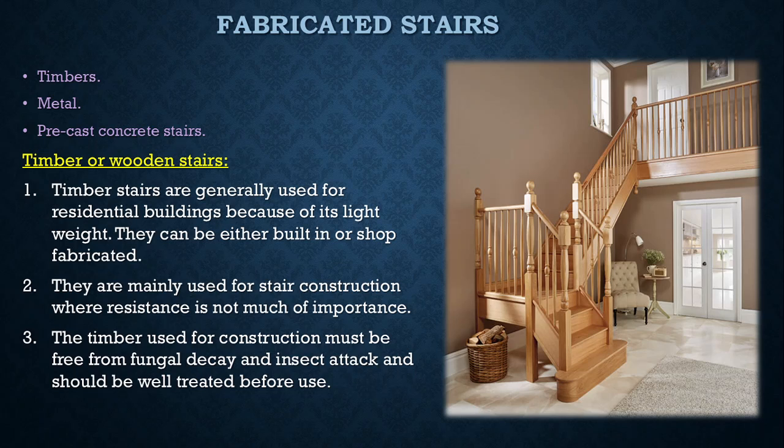The timber used for construction must be free from fungal decay and insect attack and should be well treated before use. So you have already studied timber and the defects that happen on the timber. So those cases you have to consider.